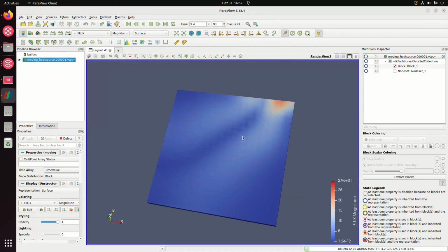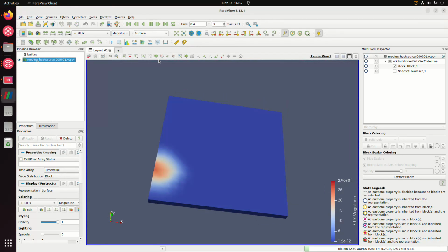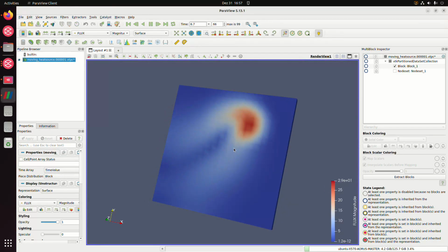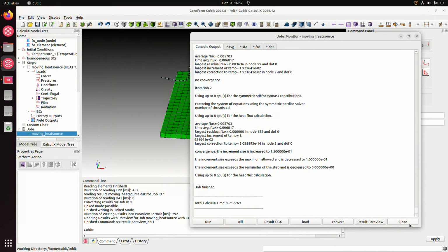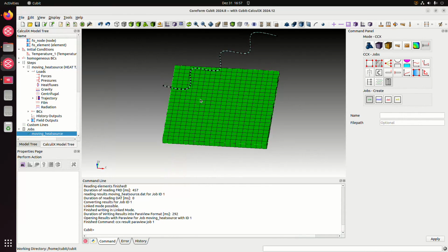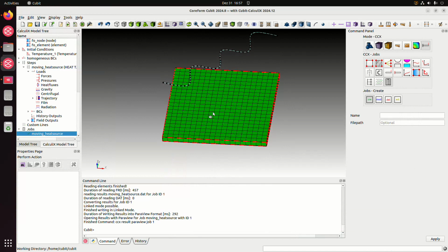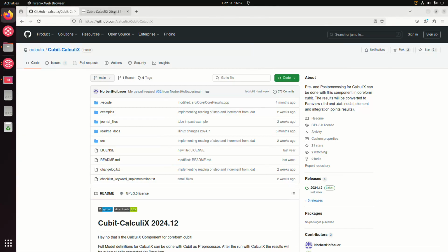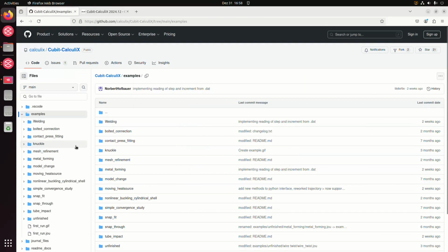As you can see, we can't really distinguish the different magnitudes, so the mesh is way too coarse for us. So we can either refine the whole volume, or we just copy paste here a bit from the examples.